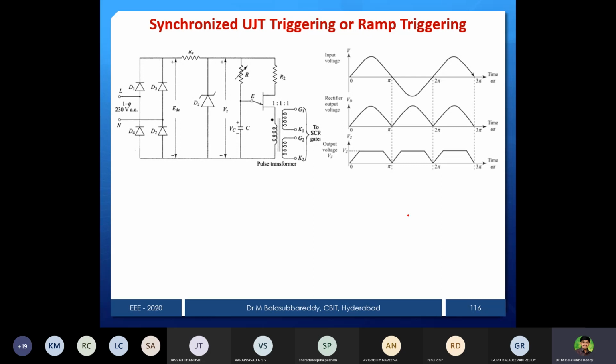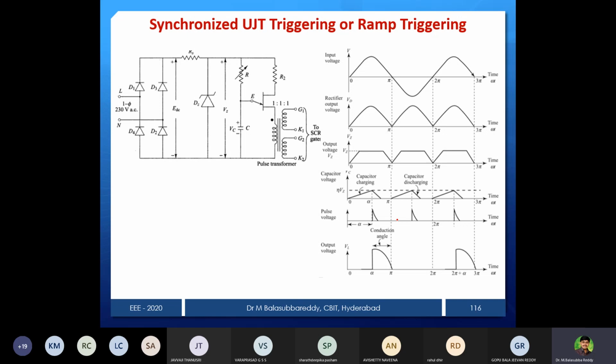And now we use a Zener diode, that's why we make it a constant voltage. We are clipping that, and after that comes charging and discharging. This is N into VZ, that is our required voltage to trigger the UJT. The transformer ratio, as I mentioned, is 1:1:1, that means whatever voltage is induced, the same pulse will be generated in the secondaries also.